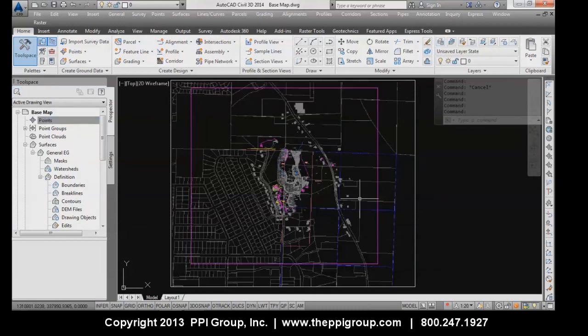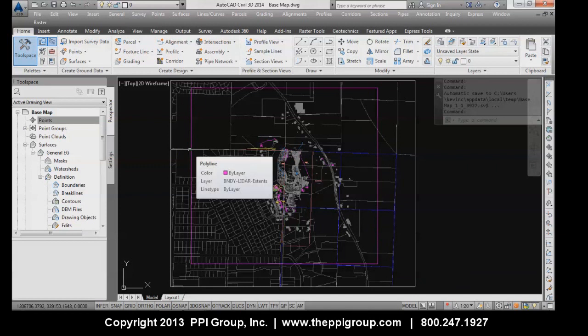Or actually, well, I'll leave that up, but I'm doing this a bit out of order here. I'm going to filter out those 805,000 points, but this will give us a good visual if nothing else. So I keep referring to this general surface, and what we're going to do is limit the extents of our general surface to that boundary after we filter out some of these points through the use of what's called a point format.